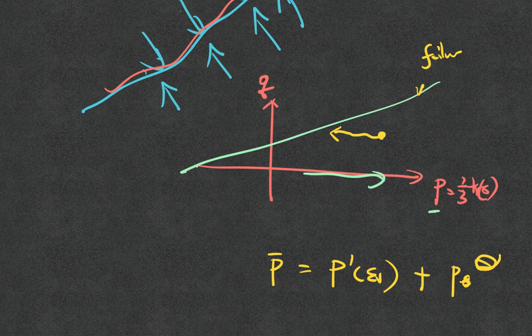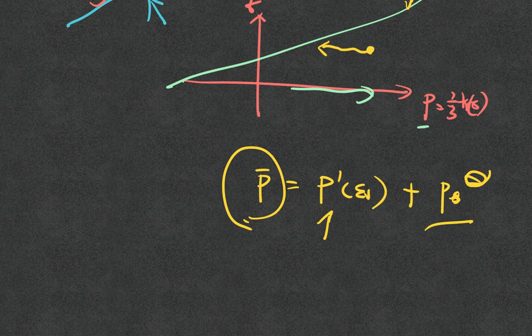Now if I have a pressure, this total pressure remains the same, but the effective stress is changing because this thing is increasing, right? You see what I mean? Or more accurately, if this one is not changing, then anything I gain from the change of the pressure will be on the equal and opposite side of the fluid pressure, right?